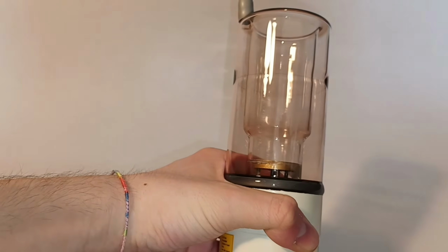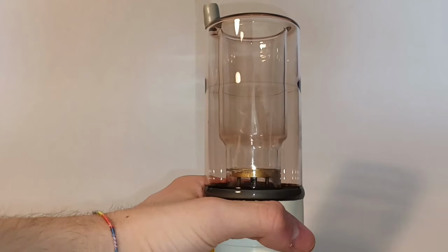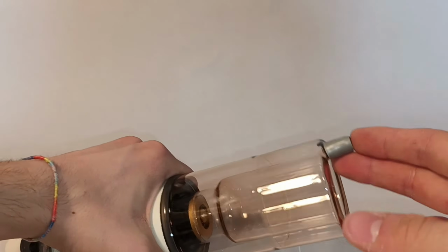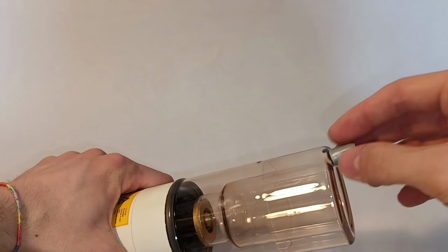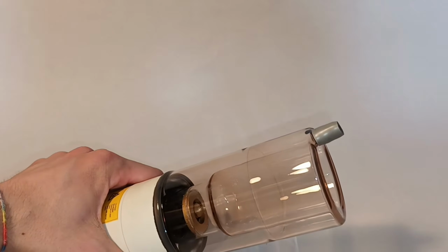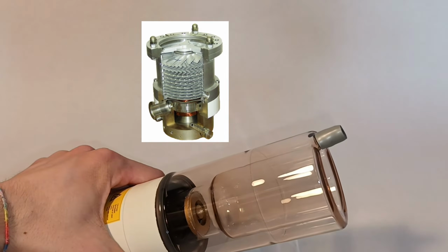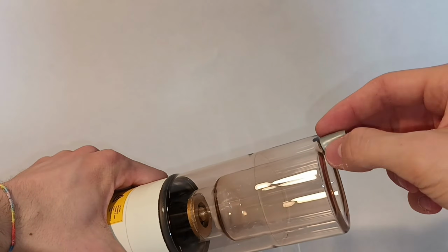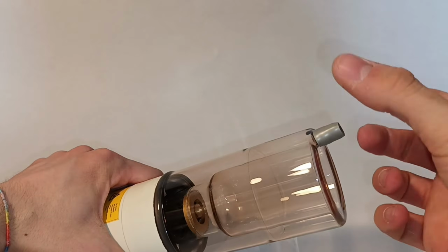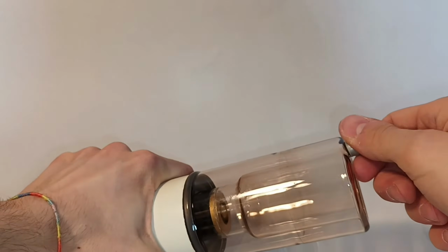I didn't tell you before, but the X-ray tube doesn't contain any air or gas, because otherwise it wouldn't work. To evacuate it, they used a vacuum pump connected to a glass tube that was connected here, and after evacuating the air, maybe using a turbomolecular pump or a diffusion pump, they simply used a flame to close the tube and to solder it shut. And then they put this little hat of silicone to protect it from damage.